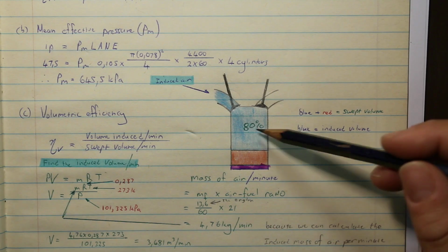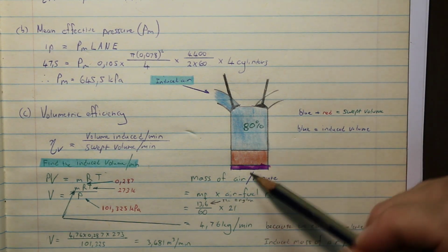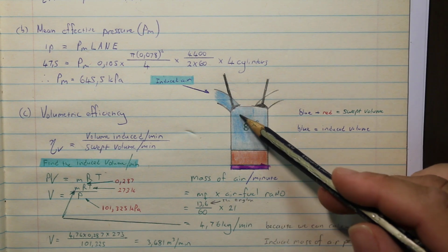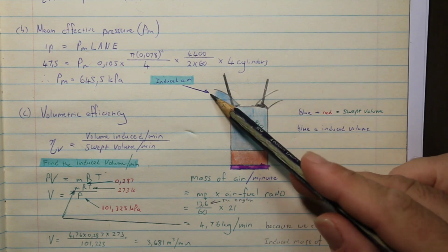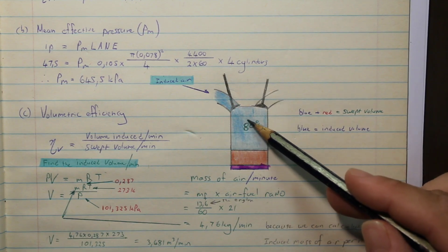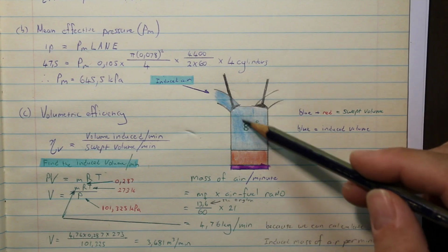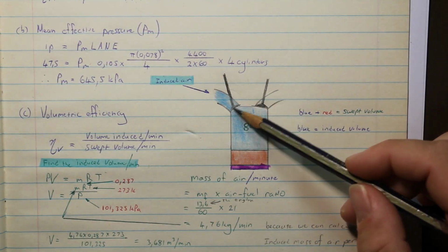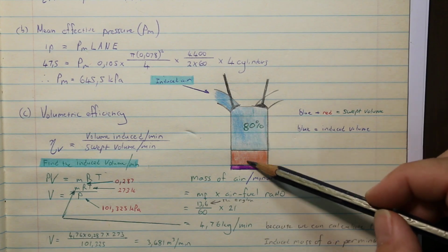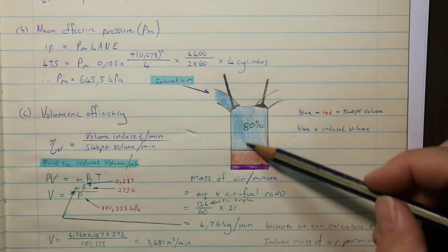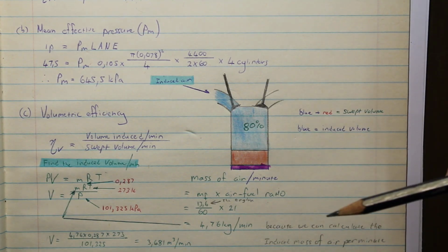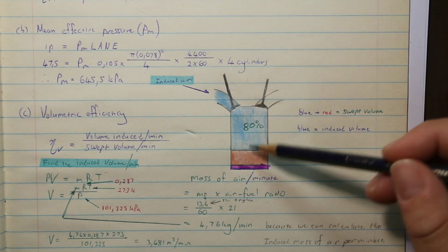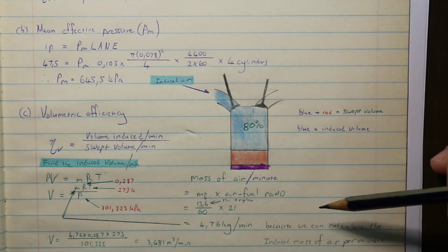So I've got this drawing here of one cylinder. The purple here is the piston at the bottom. And then we have the air intake port, so there's air coming in here. This is coming from outside, the atmospheric air they're speaking of at 0 degrees, and that is getting pulled in. And this over here is the valve. This valve needs to open up, so it slides back, and then it opens up this area here as the cylinder is moving down to the bottom. As it does that, it sucks in the air. At that time, the outlet port valve is closed because you're trying to draw in air. The engine's trying to breathe in air, so that valve is shut.